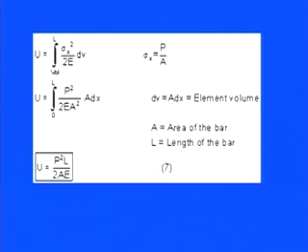So sigma x is now replaced with the force, because this axial stress is coming due to the application of force. So this sigma x is now P by A. If you replace sigma x by P by A, we have P square by 2E into A square into now dV.